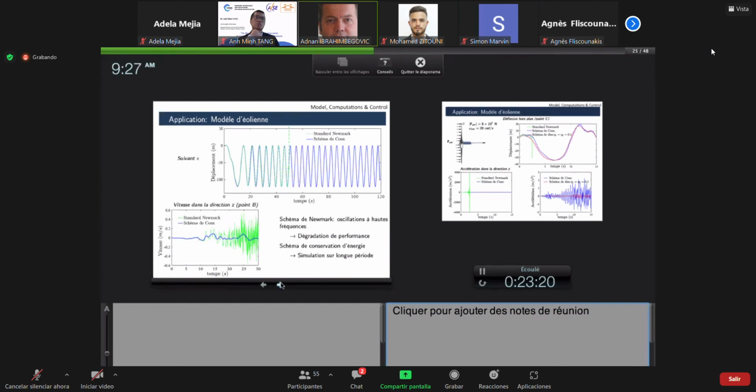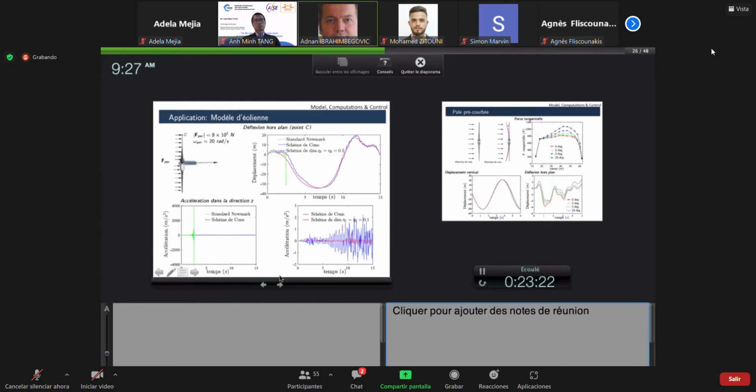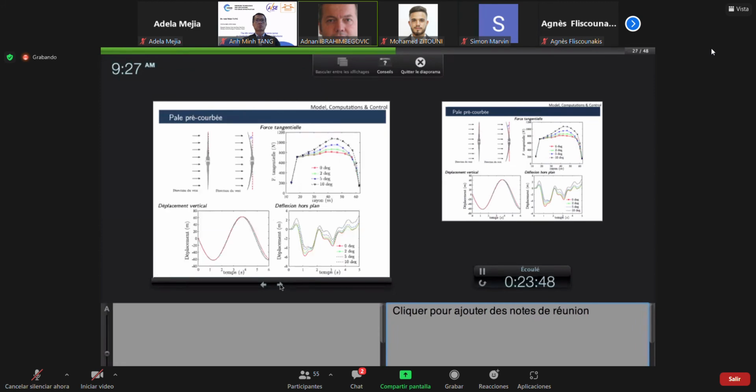whereas our energy conserving scheme goes on and on. Now, if you're looking into acceleration, even the energy conserving scheme is not good enough. Of course, Newmark explodes immediately, but basically what you need is something like this decaying scheme, because then the acceleration, your stresses, are computed as something meaningful over a long period of time, even if your finite element mesh is not excessively refined, that you have very, very tiny elements to be able to represent the high frequency modes. So you can do that with a reasonable mesh, but do this approximation in a better way.